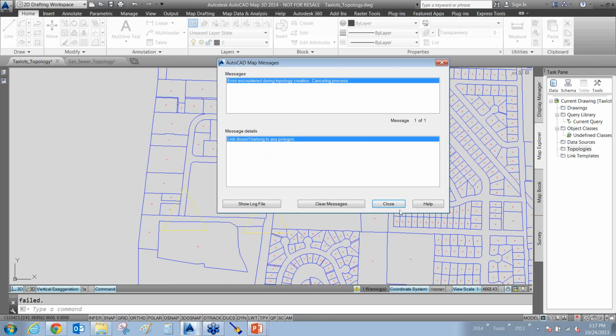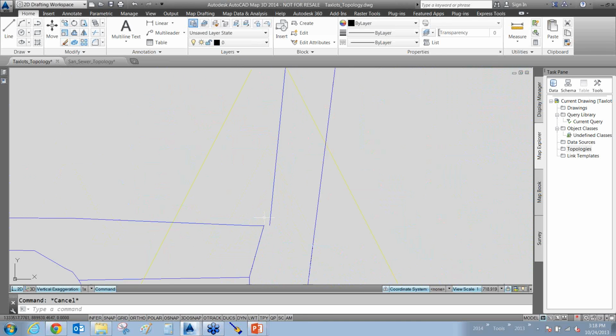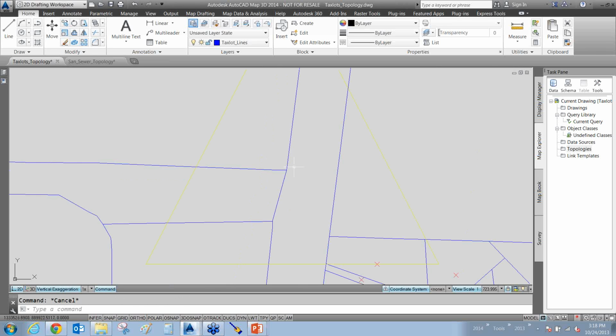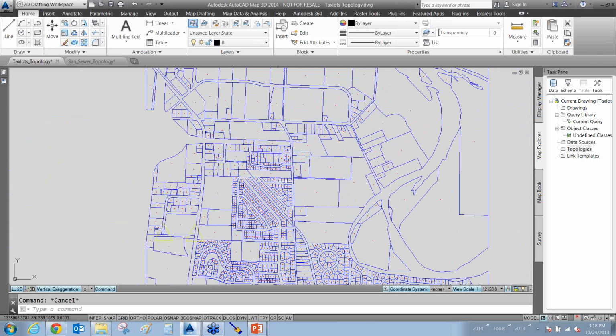I've got a drafting error. Yours may have more than one drafting error in there. So what happened? This link that goes from endpoint to endpoint, it says that it doesn't actually belong to a polygon. I'm saying, yeah, it does, but whoops, drafting error. All right, somebody did use object snaps, things like endpoint to endpoint. So, rule of thumb here is that if it's got any drafting errors, don't worry, the program's going to be more than happy to show you where they are. Now, for those of you who may not know, what happens if there are way too many drafting errors?